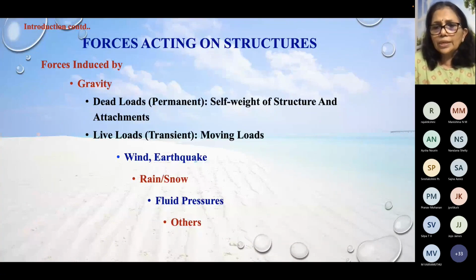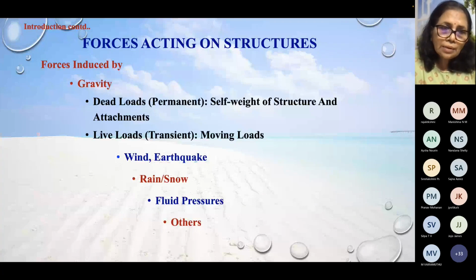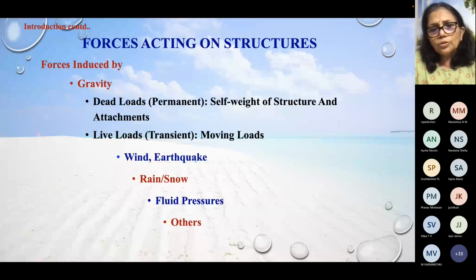When the machines are working in a structure, on a floor, there will be loads, the vibrations induced in the structural elements. So those elements should resist those vibrations also. So those loads also you have to consider. So it all depends upon what is the type of structure you're designing.